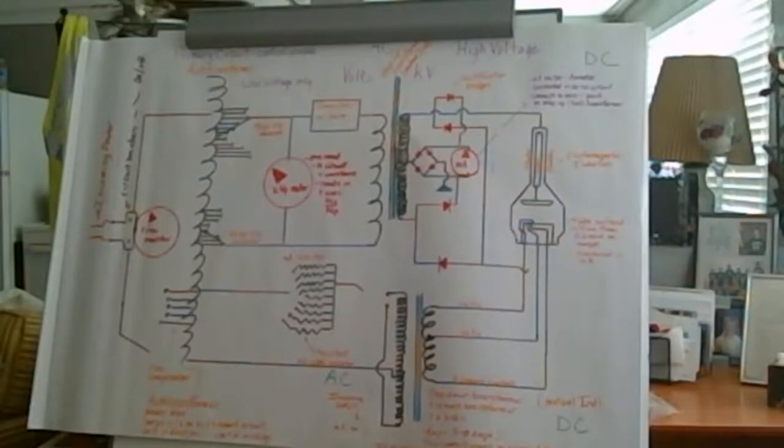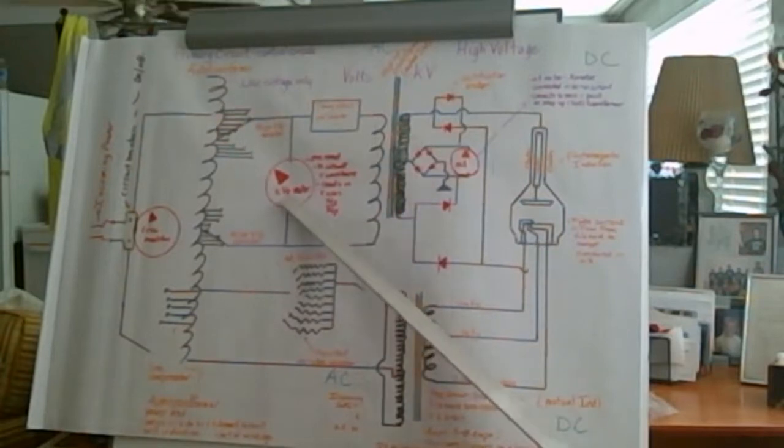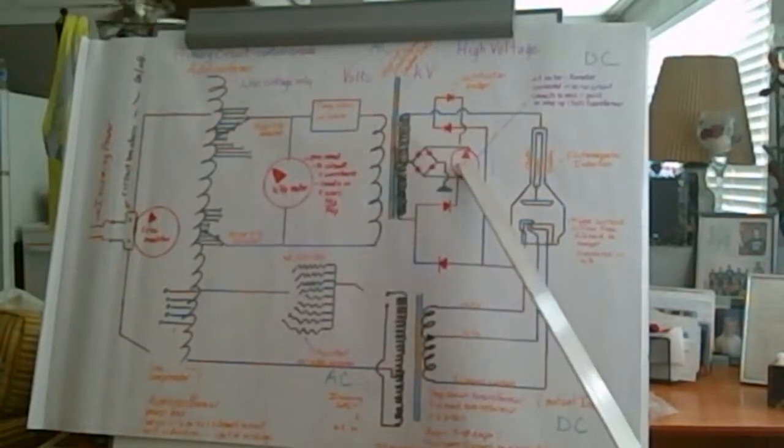If you have the more expensive Christmas lights and one light goes out, then that light's out and all the rest of them are still working. So at that point you say, okay, that's the one that's out. I shut it off, pull it out, replace it, and voila, it's working again. Those are connected in a parallel circuit, so everything else continues to work except for that one bad bulb. That gives you a little explanation of how this one is parallel and this one is in series.